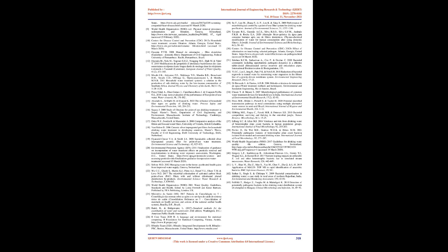Therefore, the use of traditional ceramic candle filters would be more indicated to situations in which microbial removal is the aim of the POU water treatment, whereas ceramic candle filters with activated carbon should be preferably used if POU water treatment targets the removal of chemicals, although it may enhance the microbial risk. On the other hand, none of these filters should be used if the water source is well disinfected and presents an adequate level of remaining free chlorine to avoid recontamination of drinking water during storage.